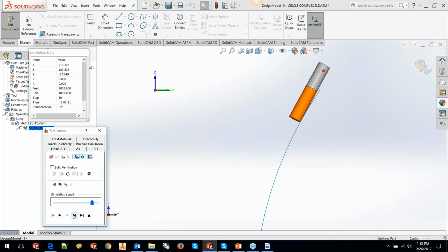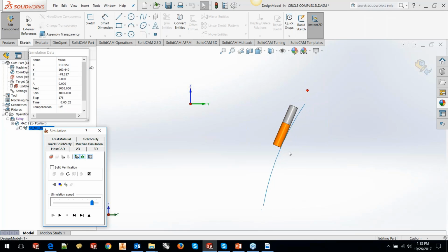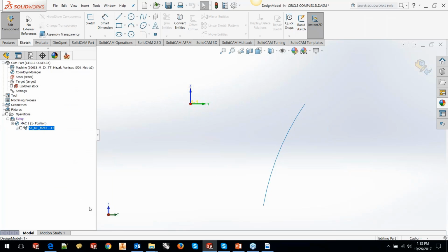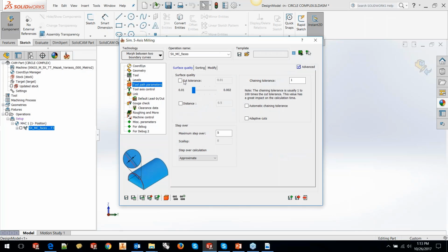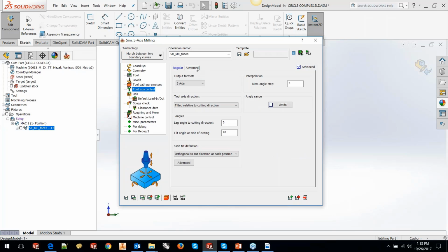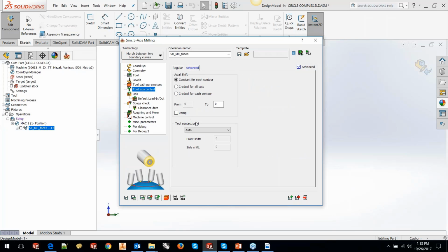The same point is in contact as it goes down. So what's actually going to happen to the tool is, this portion of the tool is going to wear out much faster than the other areas of the flute. So the customer asked whether we could shift the contact point while we were doing the cutting. It's possible. Of course, I did not have the answer at that time. There is a function here called axial shift.